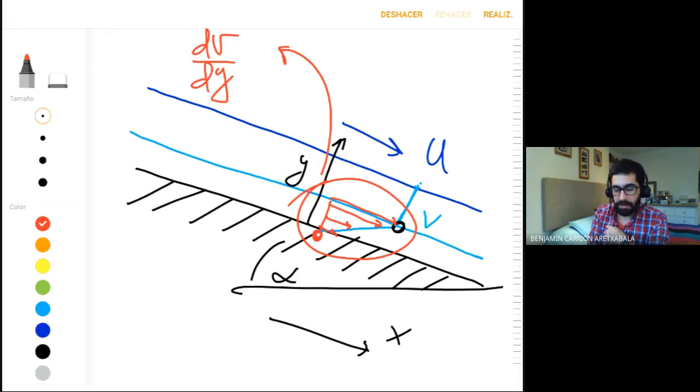So this deformation rate is going to be proportional to the stress that's being applied onto the water. So the stress here, I'm going to put it as a tau, which is normally the name. So tau is the shear stress, and it's going to be proportional to this strain rate. This is key to the definition of viscosity and of fluid dynamics.